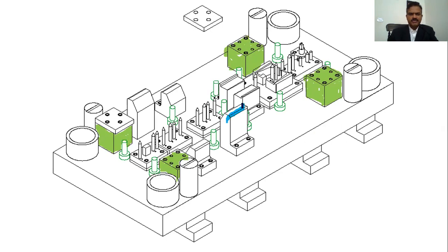So the drivers, of course, this is the taller one, which is the driver for the bypass cam. We have already discussed why it should be taller than its counterpart, which is the pierce cam driver. You can see it on the opposite side. Right from this picture, you can understand this is taller than the pierce cam driver. So the bypass cam driver can be painted blue. Since this is taller, it's going to engage the bypass cam earlier than the pierce cam driver can even get to rub on the cam itself, right?